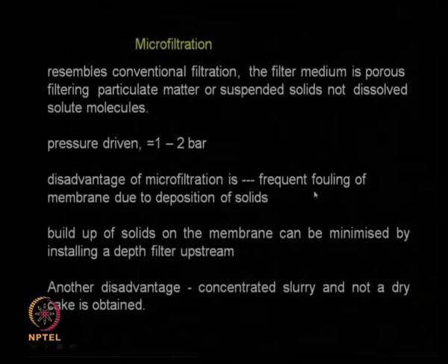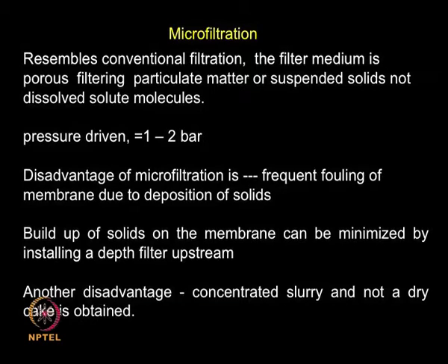Fouling, I did mention about fouling last time. Fouling could be bacterial or biological in nature, or it could be because of polarization, that is concentration polarization effects, and so on. So microfiltration does come across this problem, both the fouling as well as the deposition of solids.